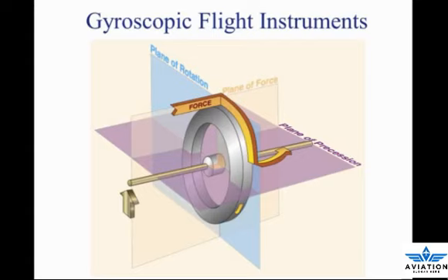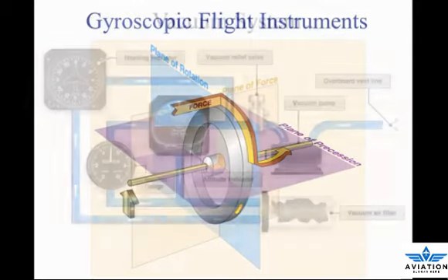There is a need to turn the handlebars at low speeds because of the instability of the slowly turning gyros, and also to increase the rate of turn. Precession can also create some minor errors in some instruments. Precession can cause a freely spinning gyro to become displaced from its intended plane of rotation through bearing friction, etc. Certain instruments may require corrective realignment during flight, such as the heading indicator.